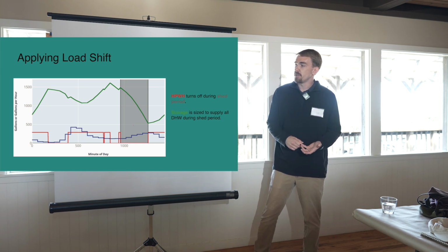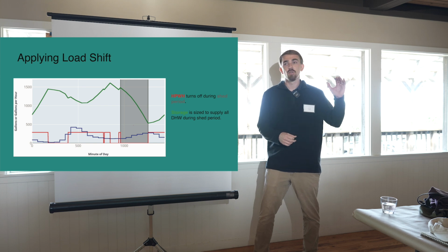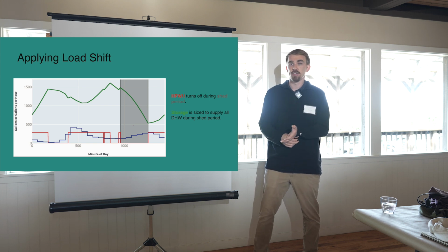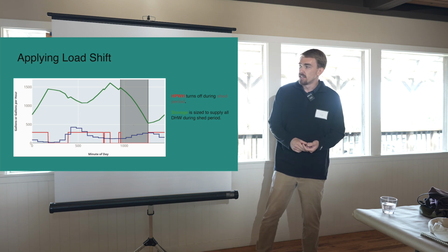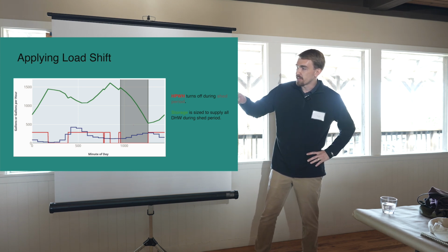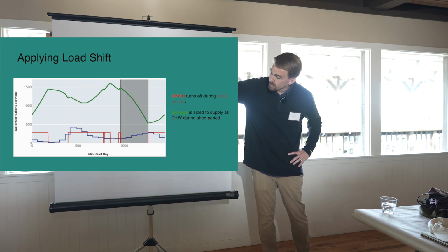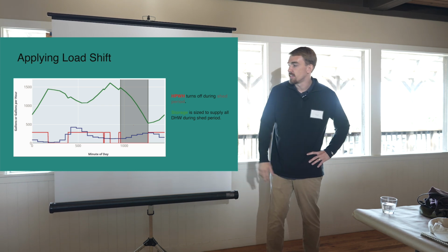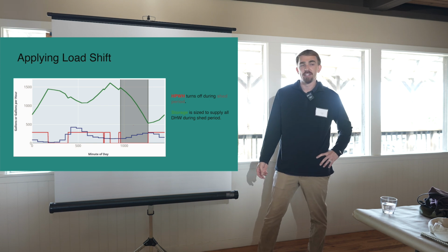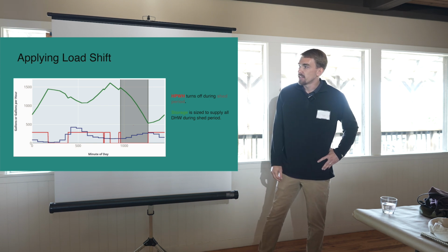So in order to do that, we just need to make sure that we have enough storage available to solely handle the peak load with the storage on its own, instead of having help from the heat pump water heater. So you can see in this plot, we'll have a little over 1,500 gallons of storage, and that storage on its own will drop down as this load happens and during what we'll call the shed period, when we don't want energy usage. So next slide, please.